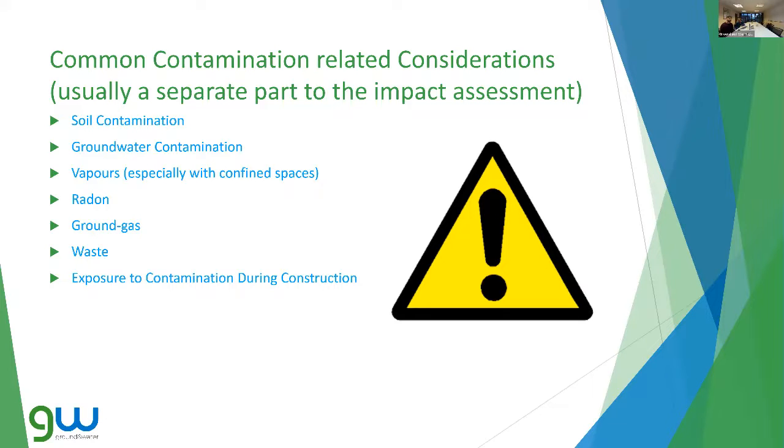So we have obviously soil contamination, groundwater contamination, but because basements are underground, confined spaces, we have more and more issues with vapors and probably radon ground gas that you wouldn't have in the same setting without a basement. So this is something that is currently a hot topic, and it will be a hot topic for the future, as far as contamination is concerned.